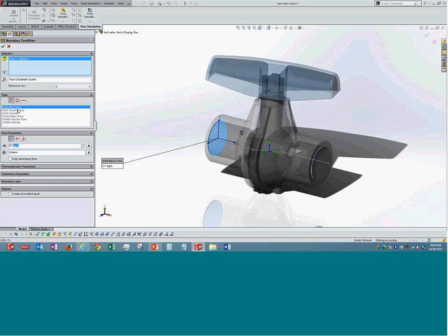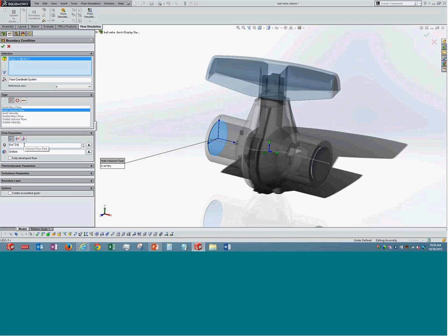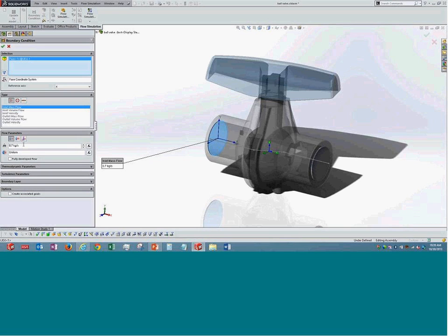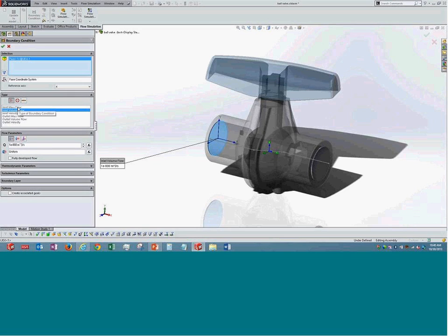So in terms of input, you can also specify whether the input is non-swirl, or if there's any swirl inside the input, or if there's any vector details that you want to view wherein the input is coming in different directions. Also, say fully developed: typically, fluid will be in a parabolic shape when it comes inside. Velocity is minimum at the ends and maximum in the center. So this behavior can be captured as the initial state itself when we are giving the boundary conditions.